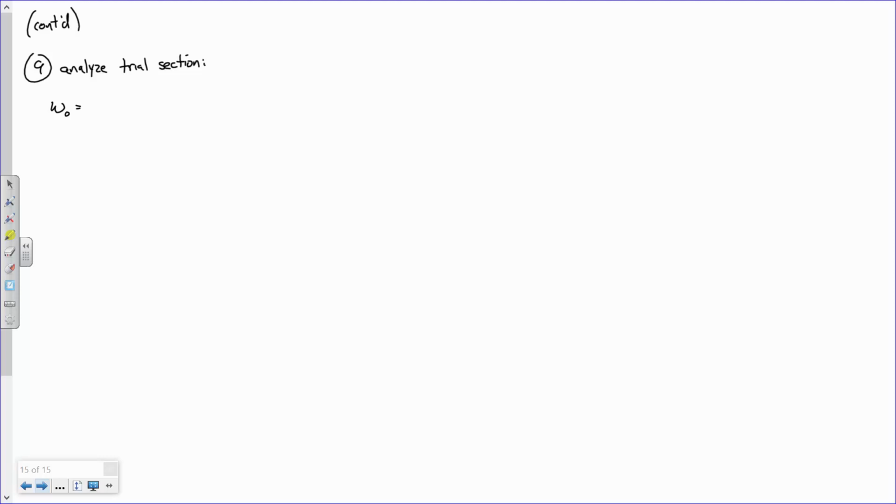So how do you compute beam self-weight? You take gamma, what do you multiply it by? The area, BH. So that's 0.15 kips per cubic foot times 14 inches times 24 inches. Notice, I'm using the real values. We now have a beam we can analyze. Got to convert our units. What do we get?